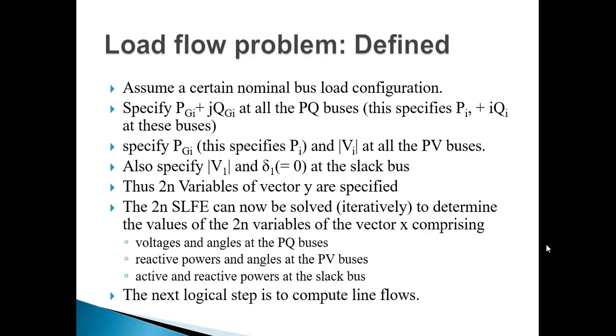So when we have a bus system, we have generators connected to those buses. For the PQ buses, we need to specify the generator real power and reactive power injection. And for the PV buses, we need to know the real power as well as the voltage at those buses.